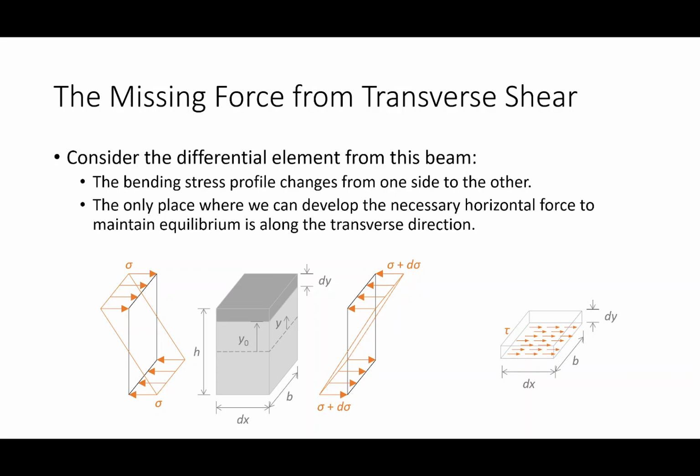So a good example of transverse shear, you have a notebook on you, okay? So if you take this notebook, this notebook is really, really bad at resisting transverse shear, because if I take the notebook and bend it, it's pretty easy to bend, right? Now, why is it easy to bend? It's easy to bend because this notebook has what? 100 some odd sheets in it, and these sheets are all sliding against one another. So, thank you. From a mechanics perspective, what I just did is I just bent 100 beams with really, really tiny moments of inertia. This essentially is kind of what I did, right?